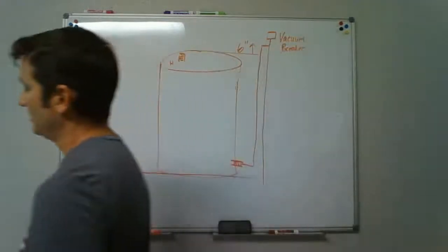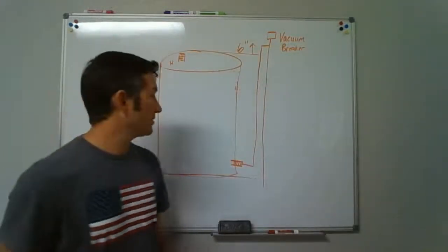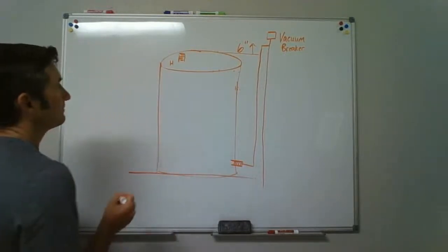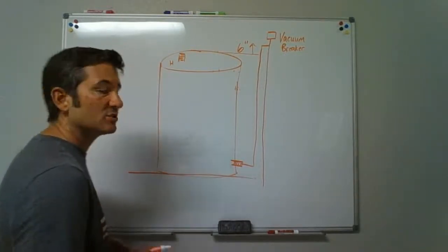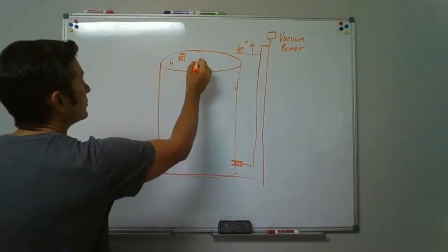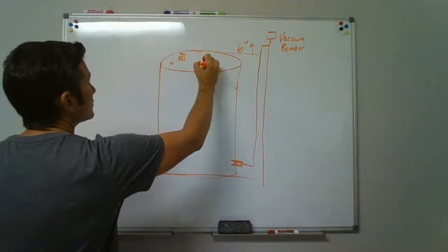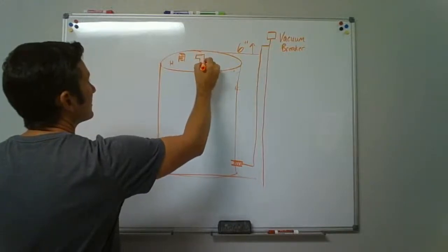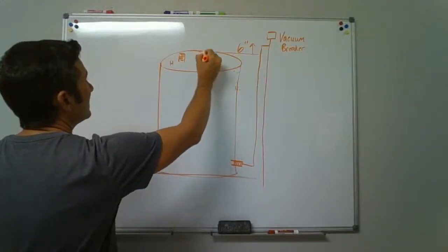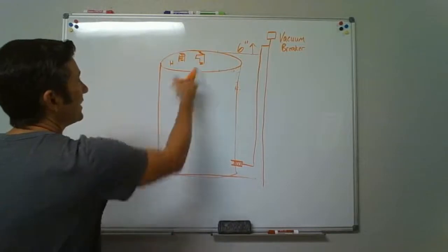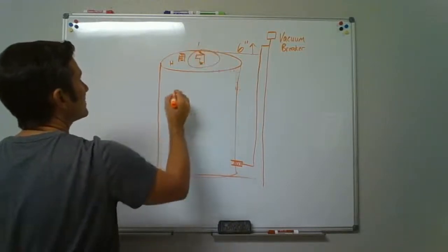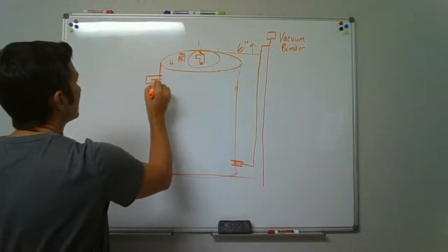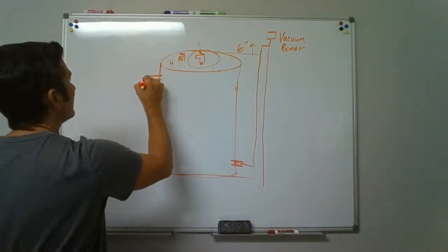Okay, let's draw our pictures a little bit more. It says, okay, we're going to have a relief valve on this thing. It's located within the top 6 inches of the tank. So you might see this installed up here. Okay. Might look something like that, and that threads into the tank. It's got a little lever on it. There's one place you might see it. Another place that you might see it is coming right off the side. Threads in there, little lever on it.